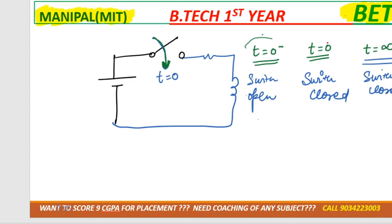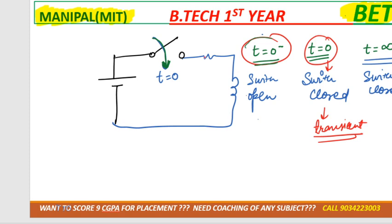So in this particular condition, at t equal to 0, the switch is closed. At t equal to 0, this is the condition of transient, because here the switch is changing its position, right? And at t equal to 0 minus, just before the close, that is the condition of steady state, because the switch was open for a very long time. Like suppose you enter the room at 8 p.m. and you close the switch, that is transient. And before that, from morning to evening, the switch was opened, so that is the condition of steady state, means the switch is not changing its position.